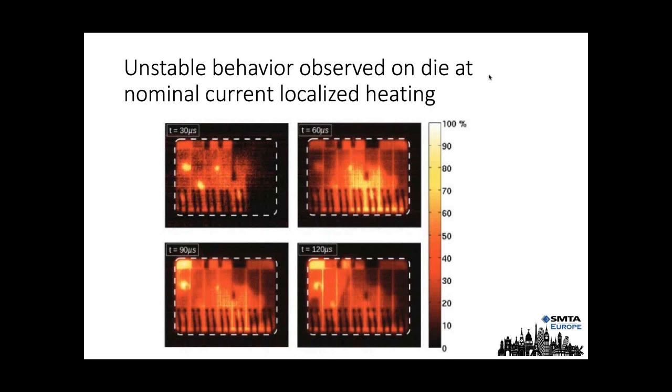The IGBT units themselves are quite expensive, but that cost pales into insignificance next to the cost of fixing some of these things that are on offshore wind farms or wind farms in remote locations. And obviously, if these are on electric vehicles and they fail, you have a whole potential series of other problems. So IGBTs and failure mechanisms are quite a hot topic, and hopefully we will cover them well